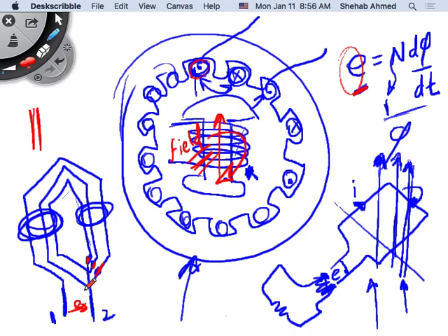At some point, we're gonna have to connect to the 400 kilovolts, right? And insulate against 400 kilovolt voltages, right? But do we want to do that inside the generator? No. It's much more difficult to repair a generator than repair a transformer, right? A transformer is a static device. Okay, you unwind the core. We look at how cores look, and you create these big bobbins of wire outside, and install them, for example.